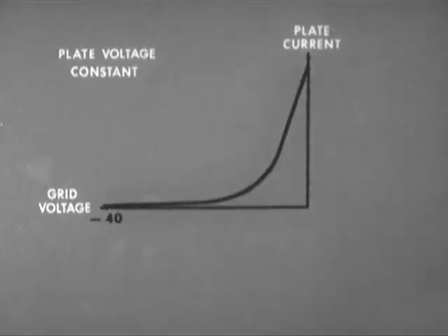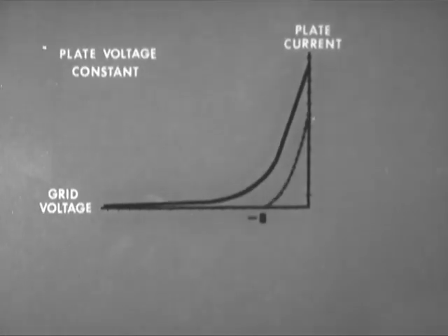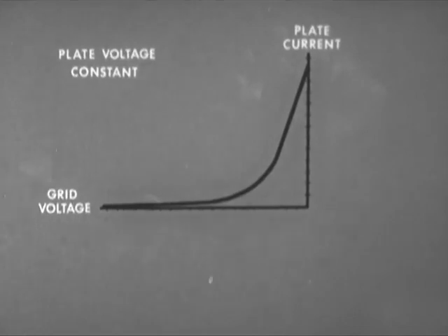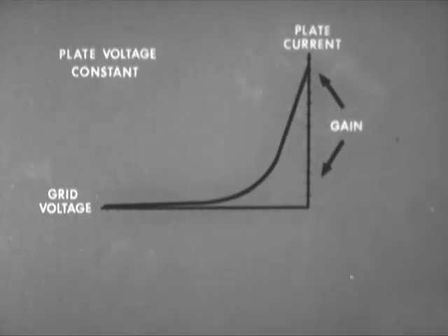If the control grid were wound in the usual manner, with evenly spaced turns, the tube would be known as a sharp cutoff pentode, and the cutoff voltage would be approximately 7 or 8 volts. The reason we use the remote cutoff type in this circuit is that the gain of the stage may be varied over a wide range simply by varying the bias.